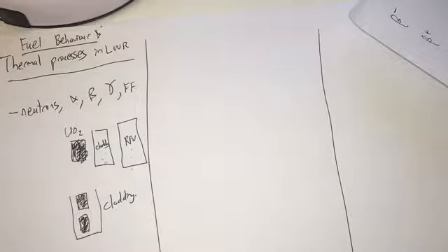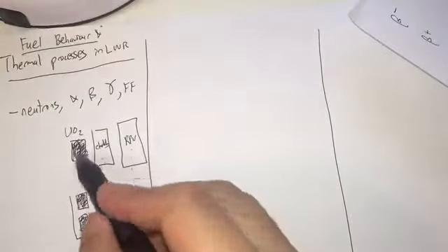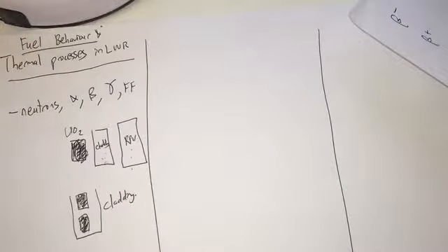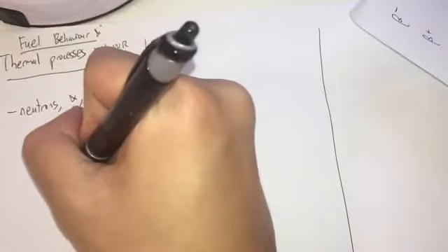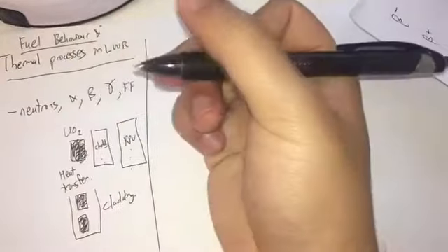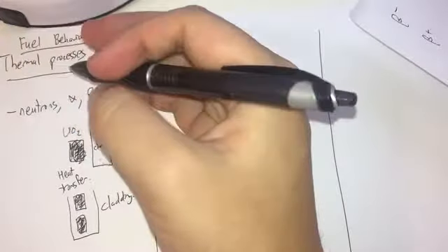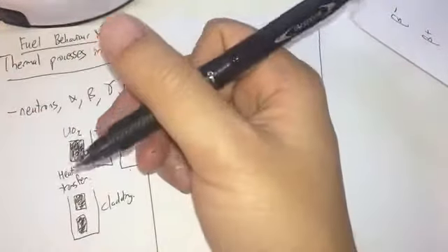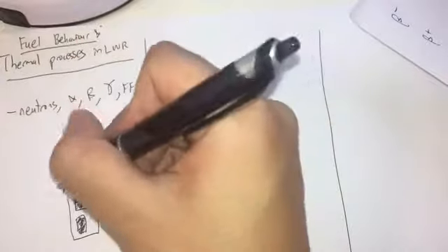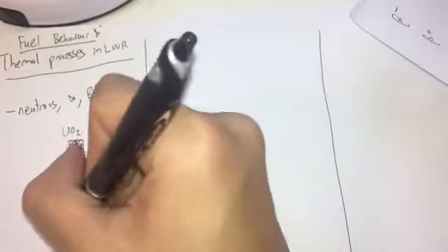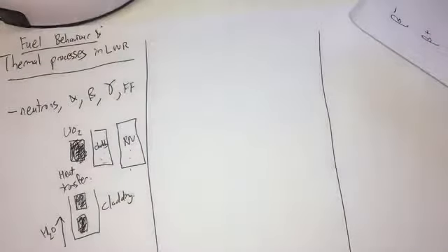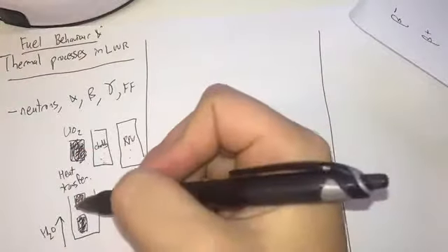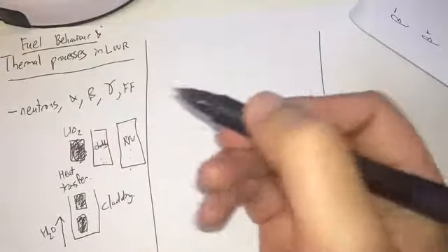Okay, what's more important? Well, for the fuel, the more important parameter is heat conduction. Why? Well, the job of the fuel is to conduct heat to the cladding, and surrounding the cladding for a light water reactor, there'll be water on the outside, either pressurized water or, in some cases, a thin film of water in a boiling water reactor.